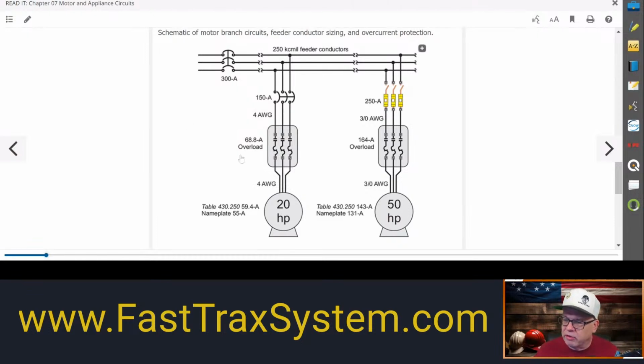So let's go on and look at here. When we did our math and we looked at our protection, obviously we've got them already here on the screen. So you've got this 250. That is your protection. You've already done the math. We already did the sizing for those fuses. And then you had the sum of the other, and that was 59.4. And that is 309.4 amps. You'll see how we got that? We did exactly what it says.